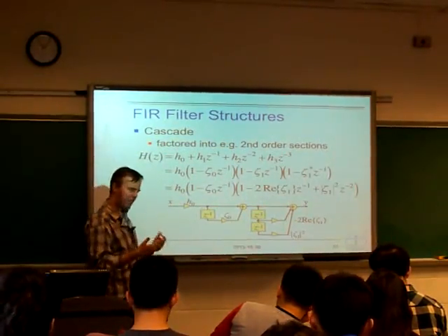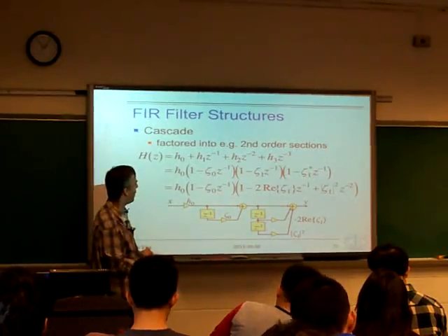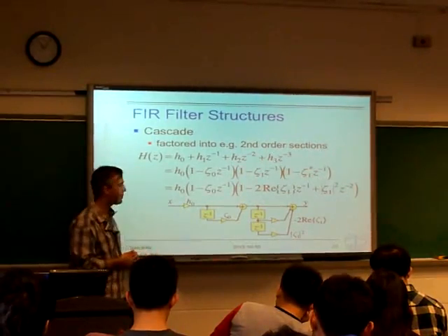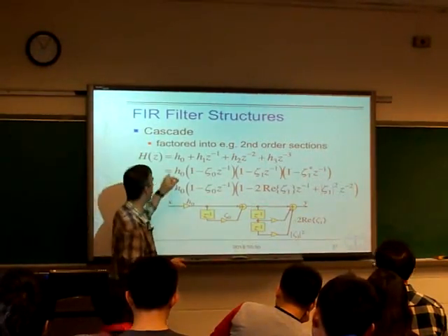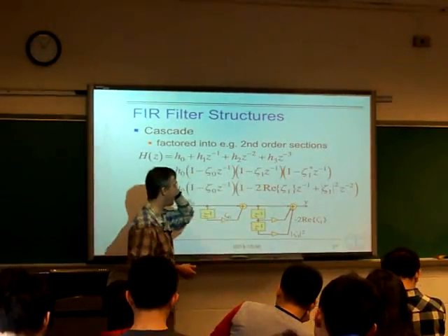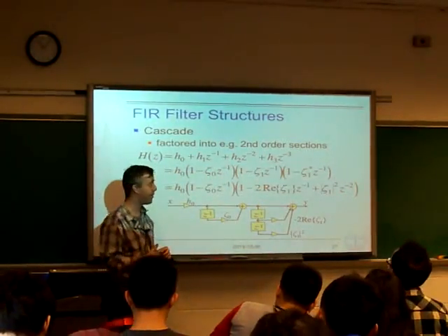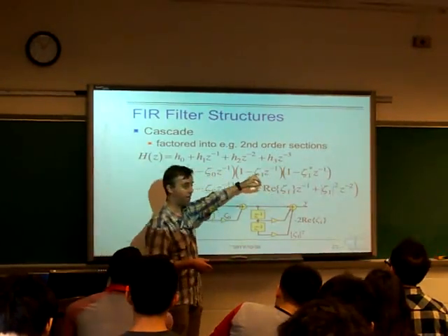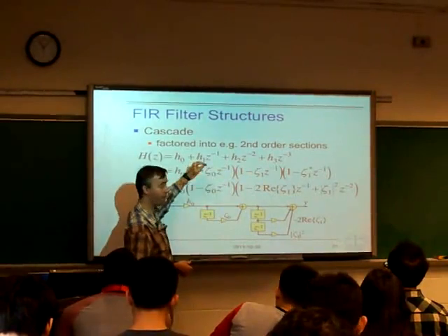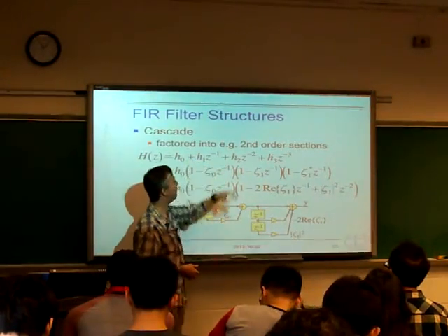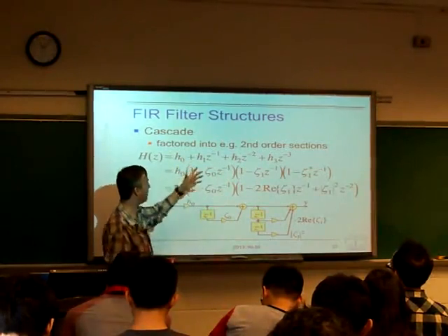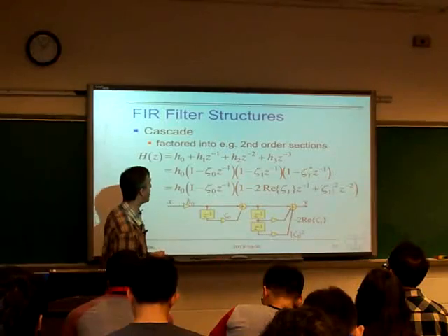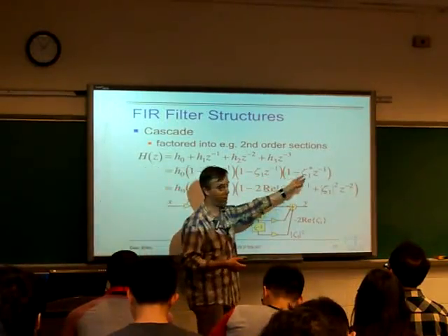One thing that we sort of know we can do with Z transforms, Z polynomials, is factor them. So, for instance, if we have a direct expression of an impulse response in terms of its Z polynomial here, well, this is just a 4-point FIR. It's the Z transform of a 4-point sequence written out directly. But it's also a third order polynomial in Z to the -1, which means we can factor it as a set of 3 roots.